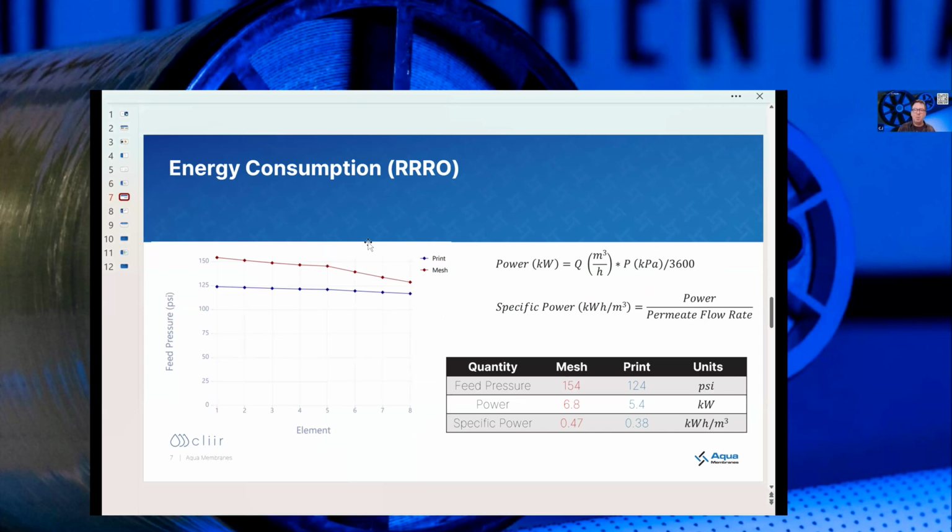specific system, where the energy saving was coming from. So before we ever loaded the system, we had done similar projections of the system at the Boise Fab. First slide is looking at feed pressure. You can see the energy savings. It's relatively simple math to convert these feed pressures into what we're maybe most used to thinking of in the water space, the kilowatt hours per cubic meter, the specific power. And you can end up getting pretty close to the observed 19%, I think it's about 20% energy savings from that difference in the feed pressure.